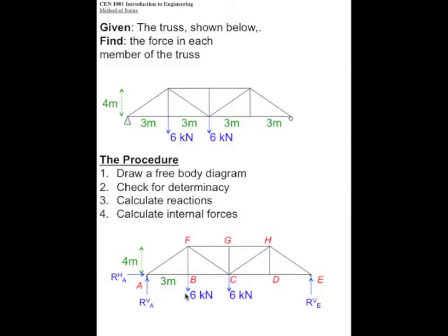The free body diagram has all of the external forces shown in blue. The dimensions are shown, and each point is labeled. Okay? Notice there's a potential horizontal component to this reaction force here. On the right hand side, this is a roller, so there's no horizontal constriction, similar to the nutcracker example from the last video. Okay.